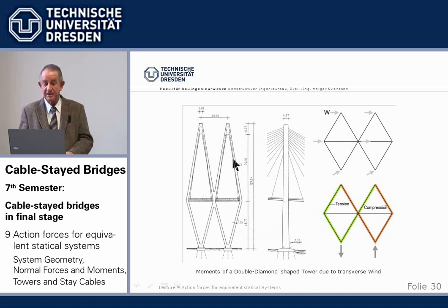That's why, in that case, we can keep constant the depths, top and bottom. In this case, we used only 7 feet, 2.1 meters for a 130 meter high tower, a rather slender structure, but it works.